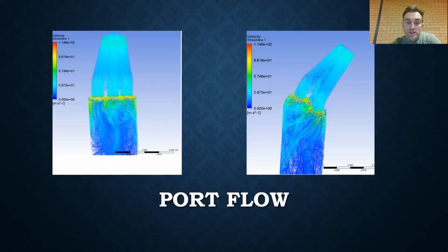For my project, I'm using the ANSYS Workbench app IC Engine, which uses a Fluent CFD solver to simulate airflow through the entire engine. There are 3 different solvers inside IC Engine. The first is port flow, which can be seen here, and this allows you to simulate conditions of what would normally be found when flow testing a cylinder head on a flow bench. It neglects the exhaust port and valves and simulates airflow from the inlet plenum through to the outlet plenum under a steady state condition.